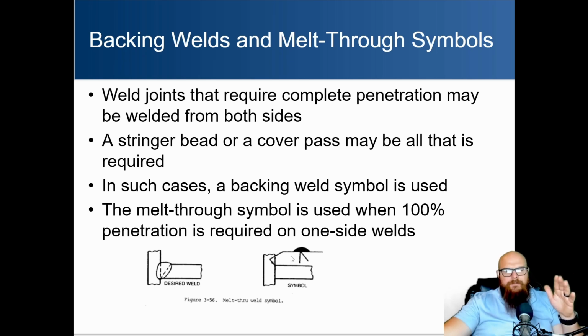We're going to have a single bevel. It's underneath the arrow side. So what that's indicating to us is that, or underneath the reference line. So that means that bevel needs to happen on the arrow side, because anything underneath the reference line should be done on the arrow side.